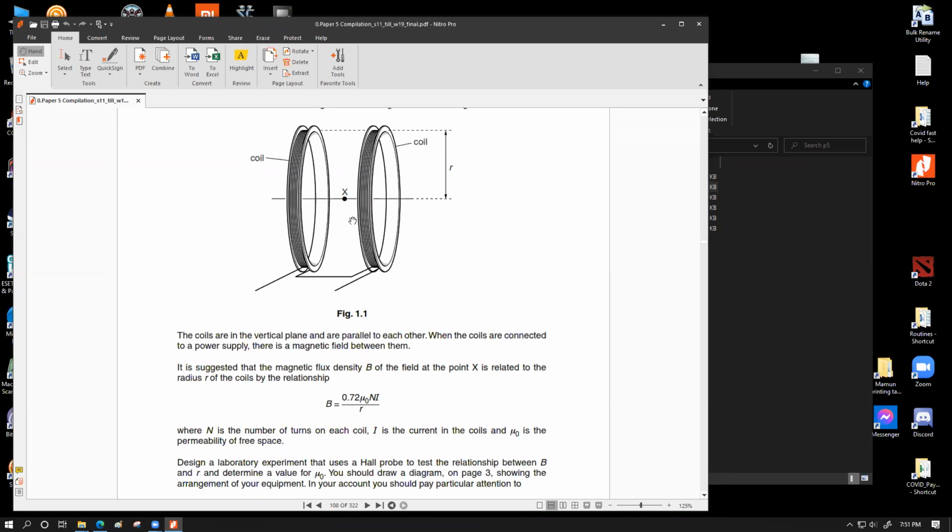One of the easiest ways is that we can tie up 2 pieces of very thin, non-metallic strings, very important, cotton strings, from this point to the bottom and from this point to the bottom. If we do this kind of 2 diagonal strings, the crossing point would give us the perfect midpoint. And this would pretty much always be the same, but we have to make sure that the distance between the two coils is kept constant for all the readings, and also the midpoint can be very easily detected.